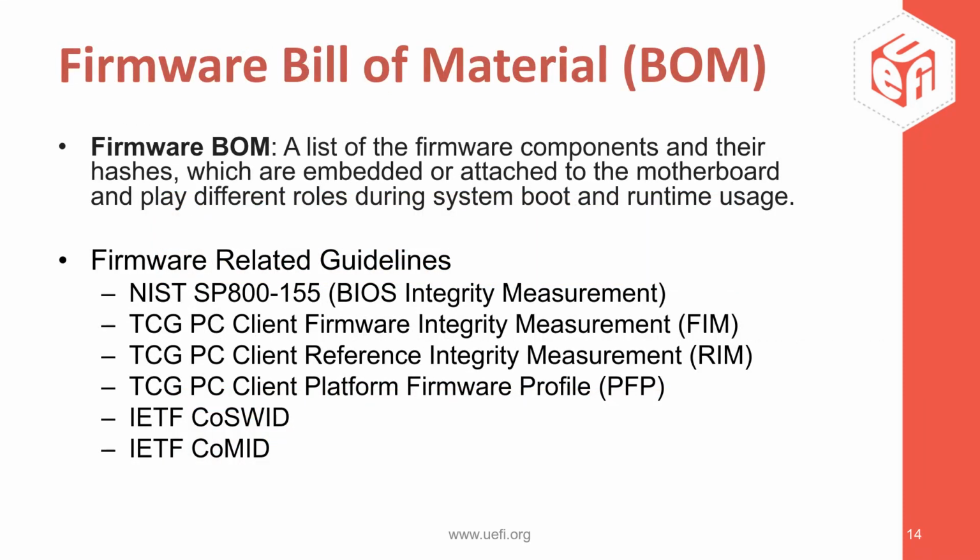So the way we get there is by the definition of a firmware bill of materials. A firmware bill of materials is a list of all the firmware components, their hashes, and class-related information for them, which are embedded or attached to the system motherboard and play different roles during system boot and runtime usage.